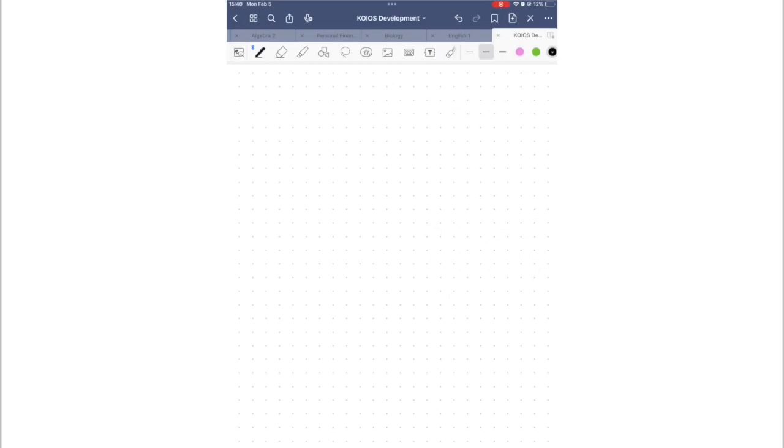Okay, so this section of the video is a little bit more centered on the actual design here. So KOIOS I is a vehicle that will have a double TVC mount, or thrust vector control system, that will be gimbaled in a direction of plus or minus 5 degrees. Now this should give me a good understanding, or a good control of the vehicle's orientation, and keep it upright or move it to a position I need to, especially during landing, but also during liftoff. I want to keep it as vertical as possible and maybe move it around.